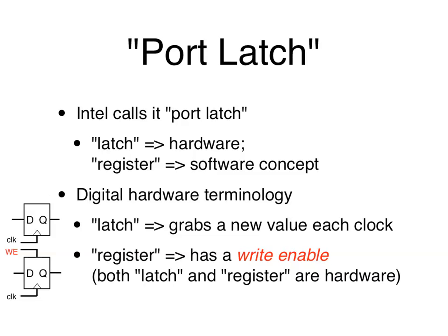There's phi 1, phi 2, and these latches allow you to build pipeline circuits, and they would grab a new snapshot of value every cycle, right? But a register does not, unless you explicitly set the write enable. Then on the next clock edge, it will remember the value. Okay? So a latch is one without an enable. A register is one with an enable. That's the standard terminology. Okay?